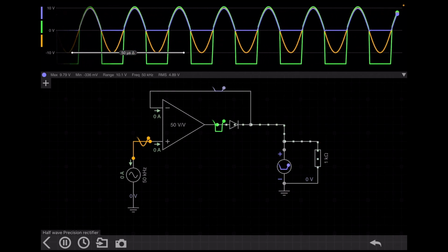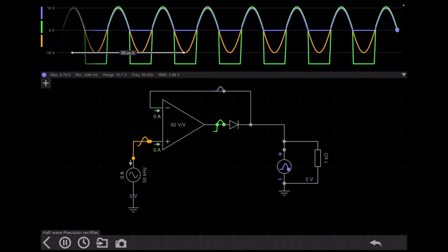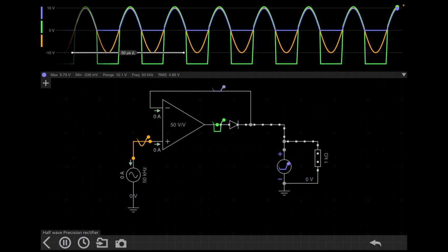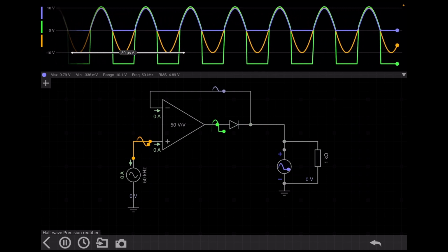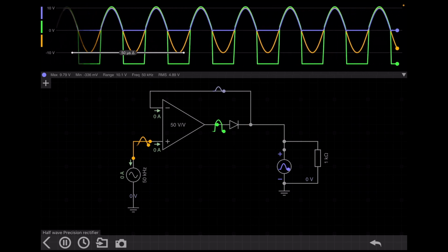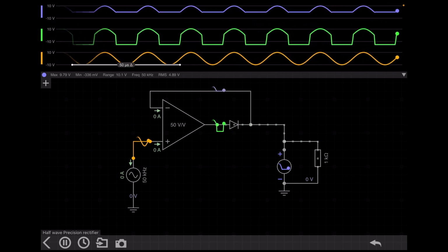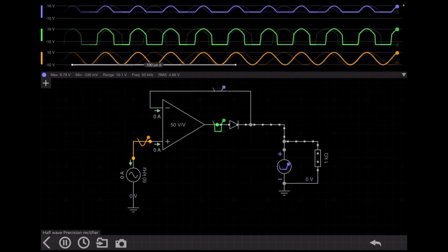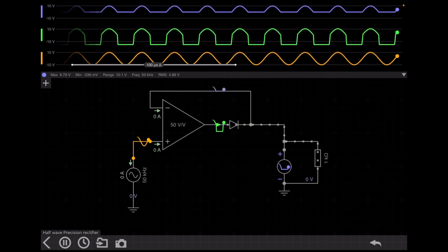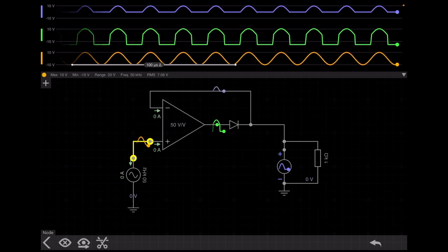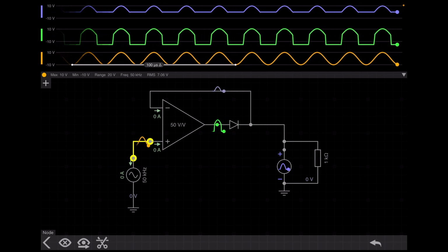If you see the voltage just before the op-amp, the green one, you can see this will follow a sine wave, okay? When the diode is on, when the diode is on, this particular circuit acts as a voltage follower. So it will just follow the input voltage, right? You can see here, just like that input voltage. But when the input voltage goes to the negative half, at that time you can see the positive terminal. At that time, I already explained to you, at the positive terminal, we are giving the negative voltage, right?